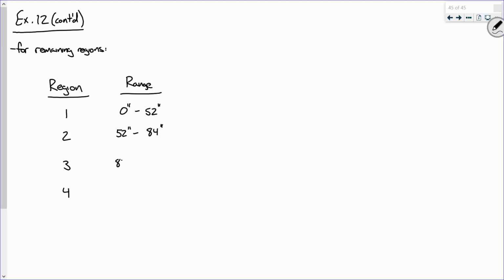And this goes from 84 inches to 124. And this goes from 124 to what? 144. And once we get to 144, we're good, because 144 is 12 feet, and that's the middle of the beam. So you can imagine it's like a mirror, it just reflects back on the other end. Make sense? So if you've got symmetric loading for a simply supported beam, you only need to design reinforcement from the support to midspan and then just repeat it. All right. So I'll fill in some remaining values.